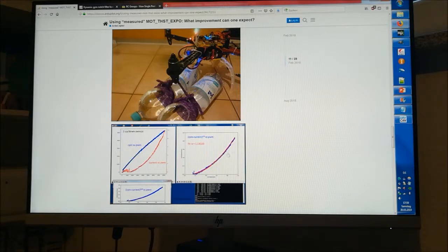One idea was to try to measure the nonlinear relationship between the RPM of the propellers and motors and the applied PWM value. This nonlinearity is accounted for in ArduPilot to linearize the PID controllers, and it is said that this improves the behavior quite significantly. So one could attempt to measure the relevant parameters here. I'm not sure how well this is really working or how important all this is, but that's one possible idea.